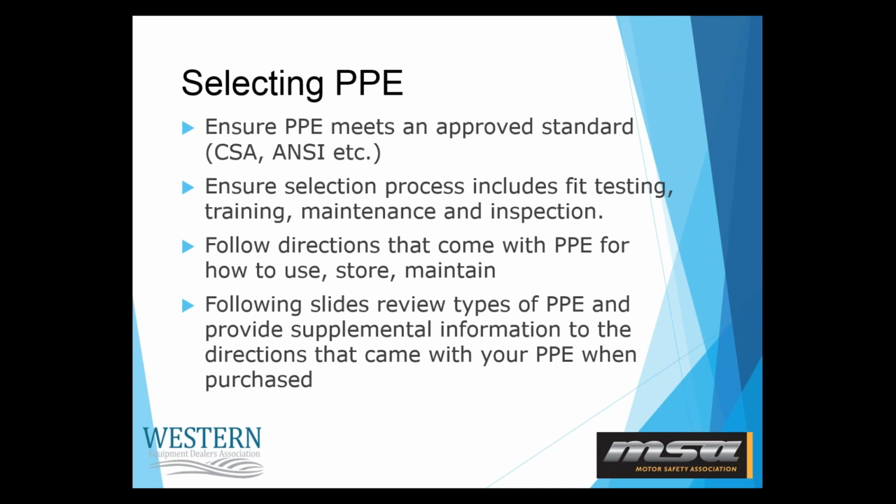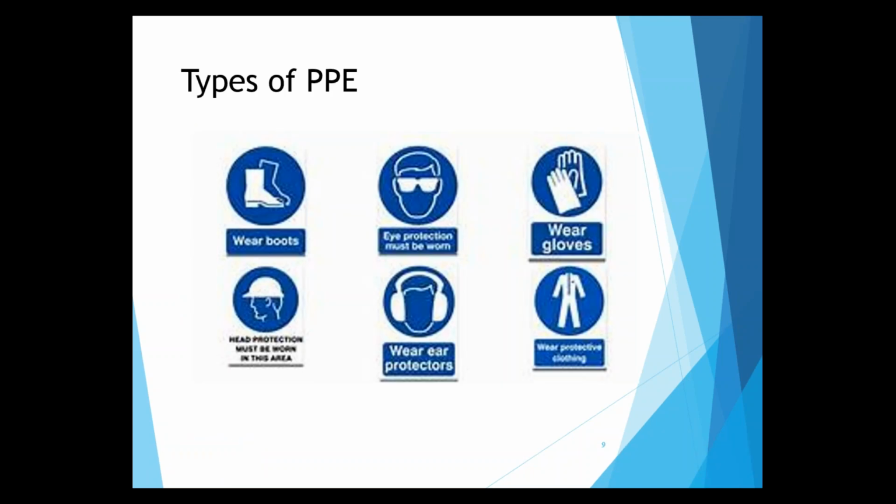So when we are selecting PPE, it must fit us properly and we must know how to maintain and inspect it. And again, follow those directions that come with your personal protective equipment for the usage, storage, and maintenance. I'm going to go through some of those tips in the following slides to give you some of that information on how to use, store, and maintain your personal protective equipment.